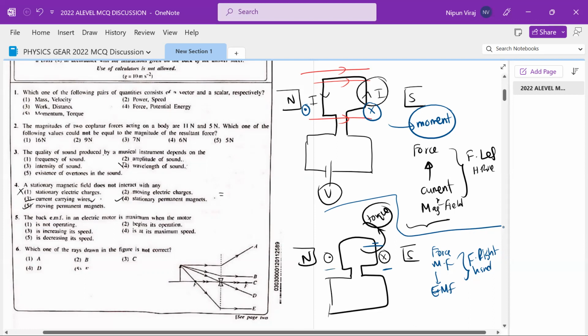And if you take the left side, the force is acting upwards. So keep your thumb upwards and your index finger from left to right. You see thumb is upward, index finger is from left to right, and the EMF will be created upwards, right? So this is what we discussed first, and this is what we discussed second. Now magnetism is okay. I hope you understood this.